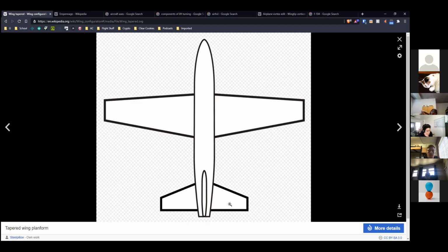See how this tail, it's mostly about tails, has taper, but since the back edge is flat, this wing has taper and is technically unswept. It's a straight wing. This tail is technically swept because the line that connects the center of its tip and its root is not perpendicular to the longitudinal axis. It has an angle, and that's technically the sweep angle.